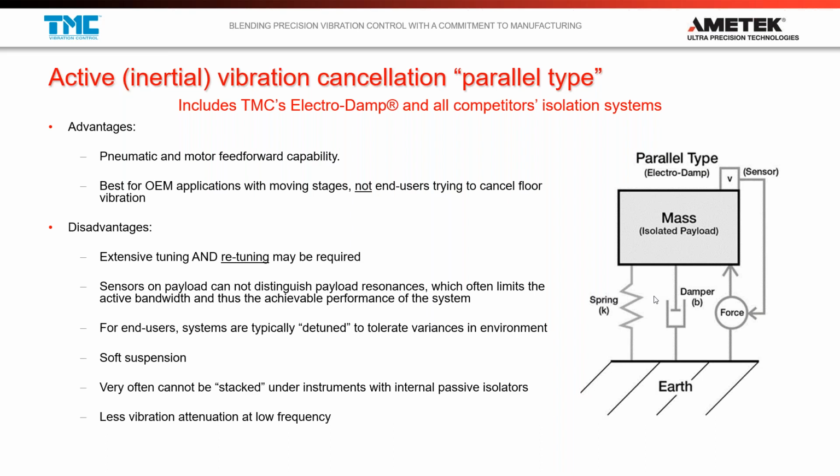What we see parallel type systems for, one of their main advantages is the fact that they lend themselves very, very well to what we call feed-forward capability as opposed to feedback capability. Their feedback performance as far as floor vibration control is so-so, but their feed-forward is really great because a linear motor is very, very powerful.